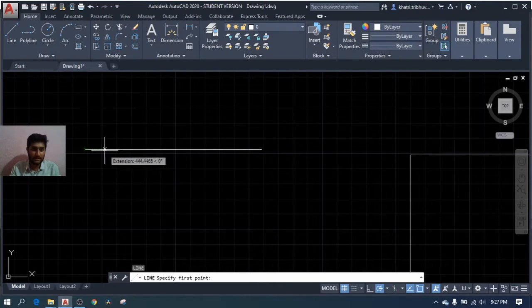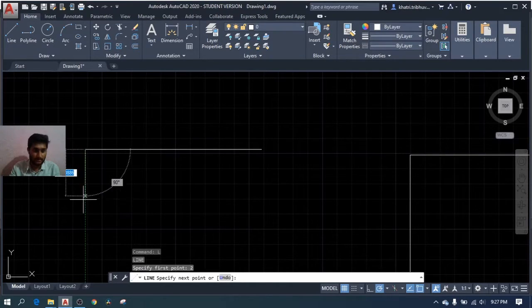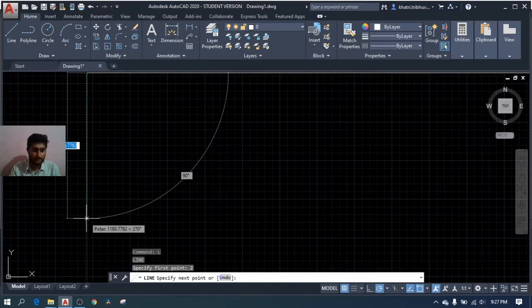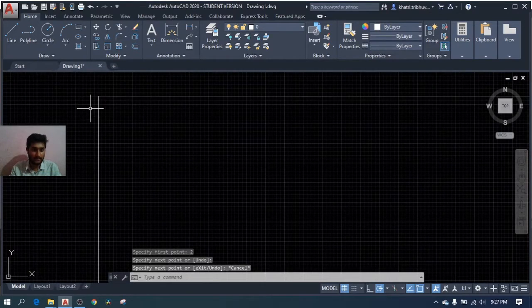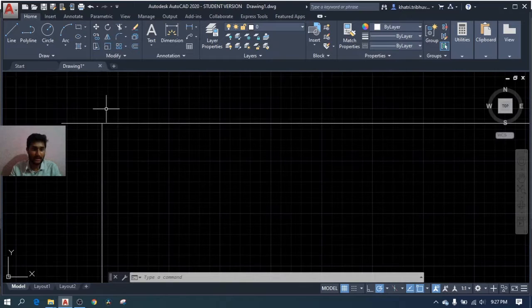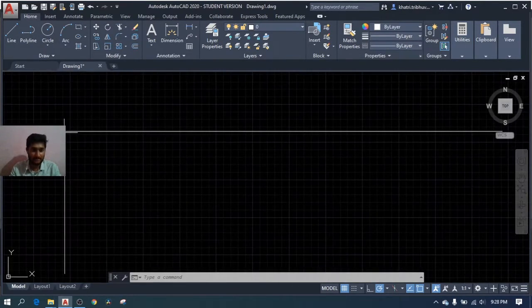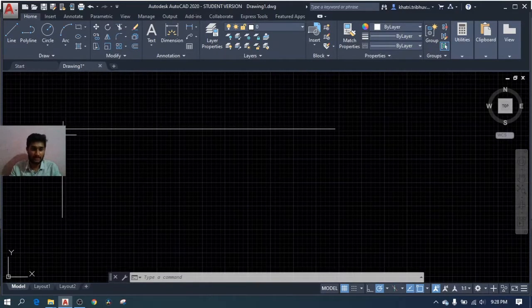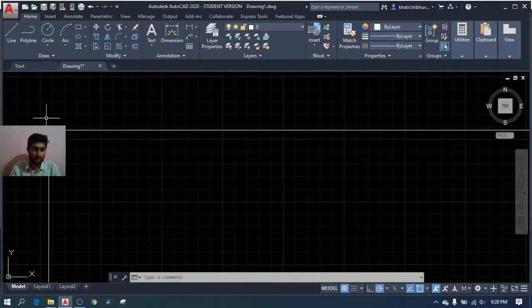This specifies that the CAD is actually tracing your mouse cursor, to know where it is supposed to start that perpendicular line. So you press 2 and hit enter, and your length is selected as 2 units. That is, you have created a line. You can see, if you zoom in, that you have created a line perpendicular to the initial line with 2 units right from the starting point. See how easy your task is due to various CAD commands.